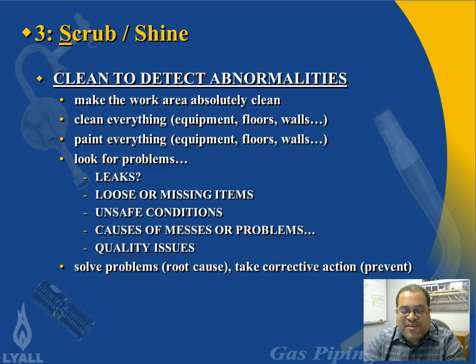Because you could see dust on the equipment, and if you have a white piece of equipment, it's always standing out. Well, yeah, it forces us to keep it clean, but if you have a white surface, you're going to see a leak before it could cause any engine damage, before it could cause any damage to motors or physical elements of the equipment. You see frayed wires quickly. You see dial indicators better. So really that's what it's for. It's so that you could detect abnormalities of whatever's left.